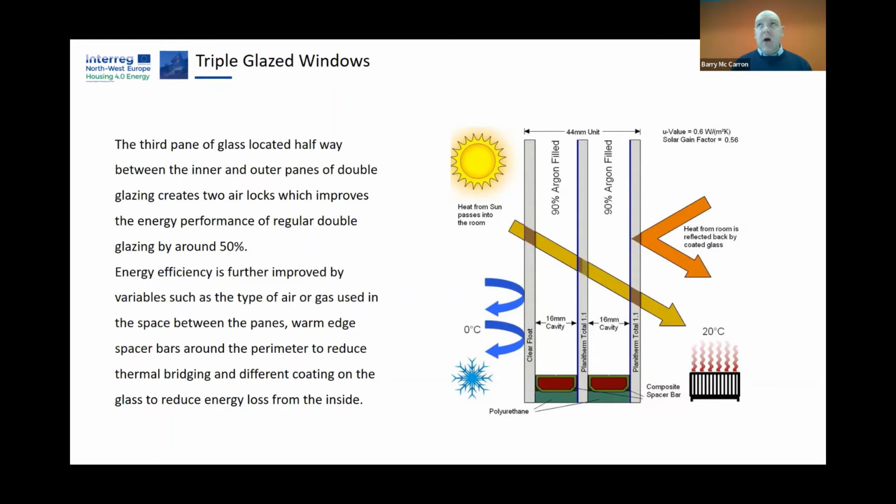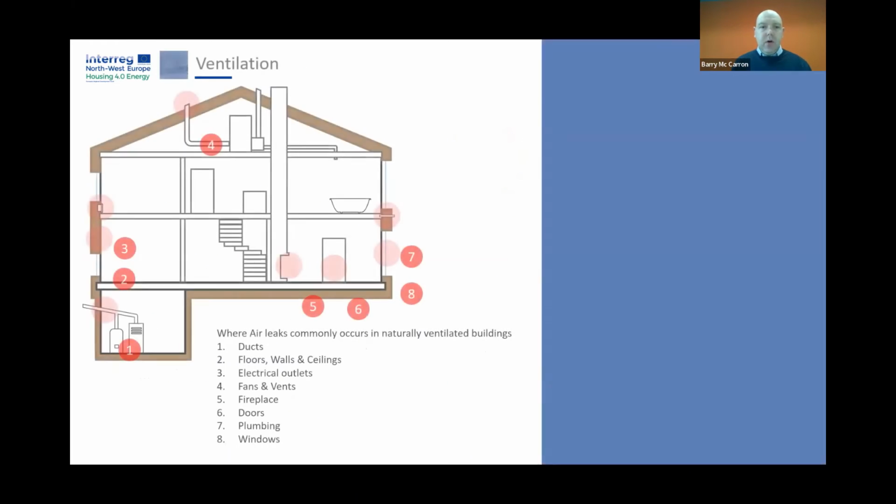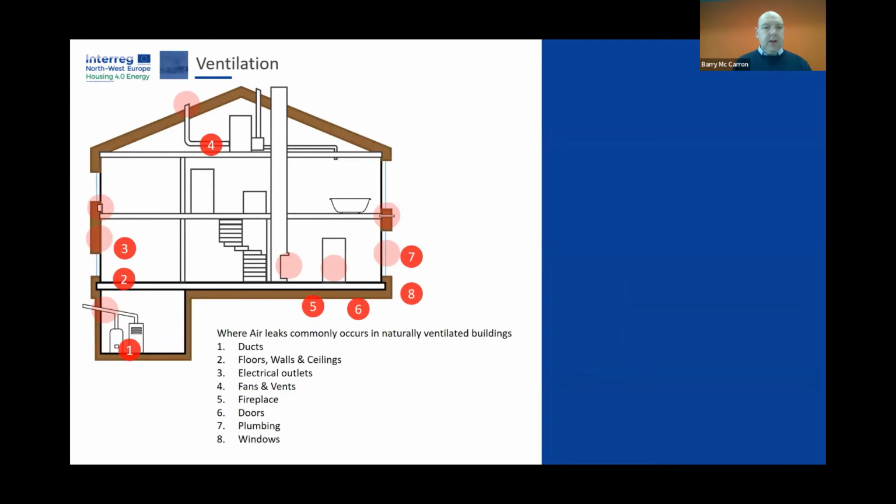So it is actually possible on some very sophisticated buildings to have different standards for the glass on different sides or orientations of the building. If you have a lot of south facing glazing, it might be worth lowering or changing the G value accordingly so that you don't end up with a lot of heat coming into the room. So that's interesting as well. And on the north side, you can do that as well.